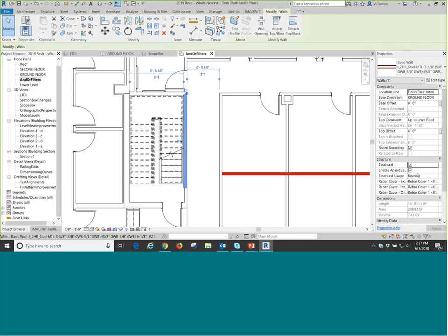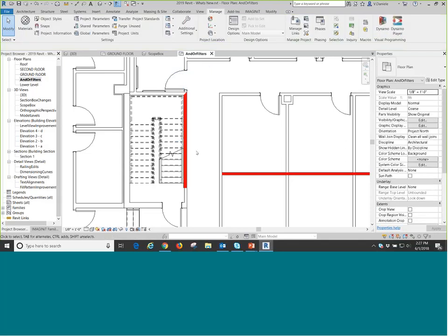If I change this to structural bearing wall, you can see that it automatically, instantly changes because it contains one of those filter subsets. So the OR statement's nice because we can highlight things that might have one or the other condition as a valid condition.